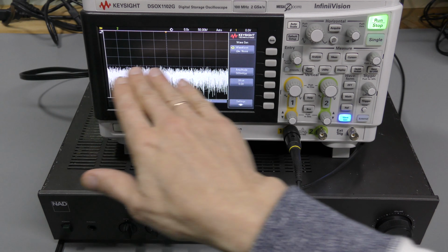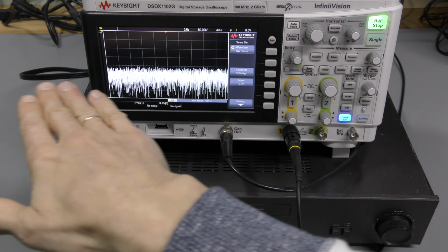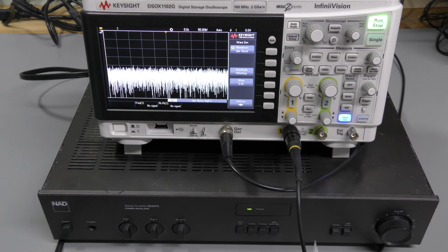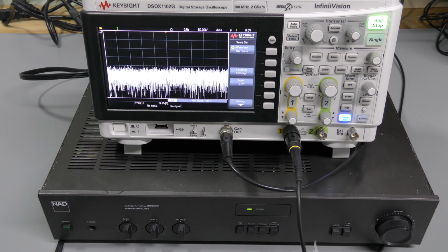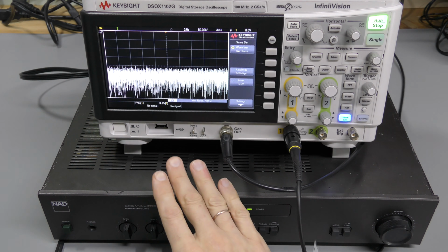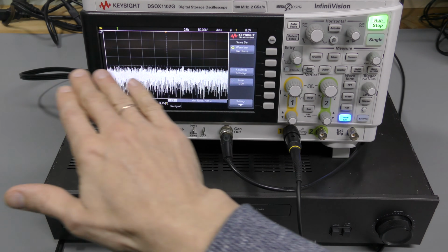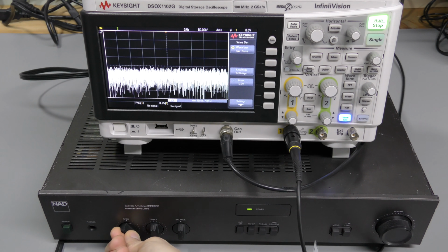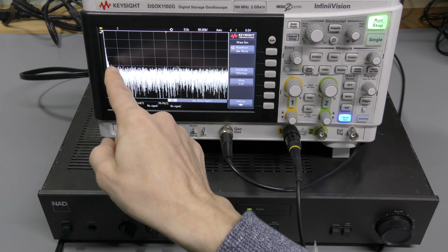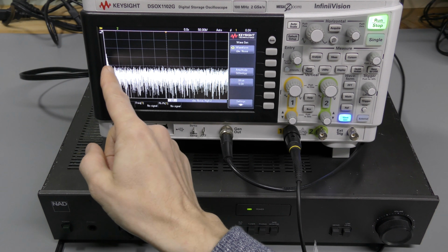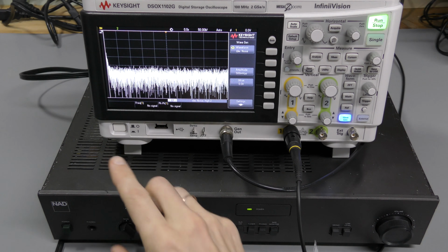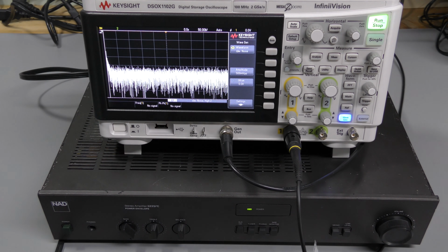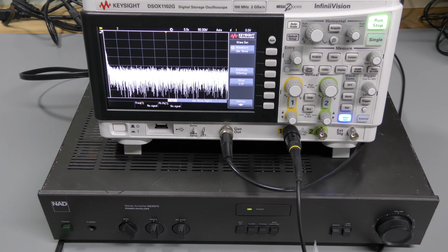So now the shape of this top is our frequency response. And because the tone controls are in the middle, we expect a flat frequency response, and it is approximately flat. Now let's try boosting low end, and here it is. And it only affects that small region here because unfortunately this is not a logarithmic scale as it should be for audio analysis.